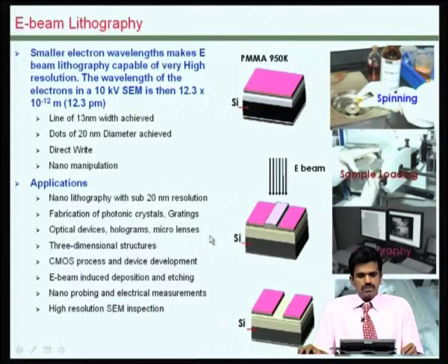It is also possible to extend these for 3-dimensional structures for microsystems applications or for CMOS applications. Some of these equipment available for the e-beam lithography can also be used for nano probing and high resolution SEM inspection of the layers that are formed.